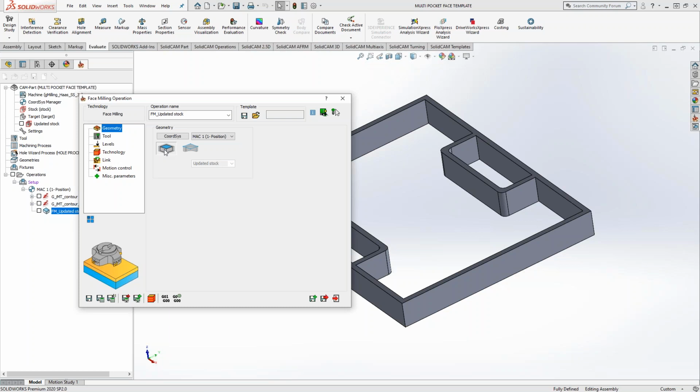This is unique, not unique, but this is actually important and interesting for a toolpath, and specifically for the template of the toolpath, because I am not telling it to select a specific geometry, but I am telling it to look at my stock definition, so you can think of that as a variable. Once I create this template and I load this template going forward, it will always look at my stock and target and figure out the geometry for me. So in terms of templates, in terms of reusability, this is key.